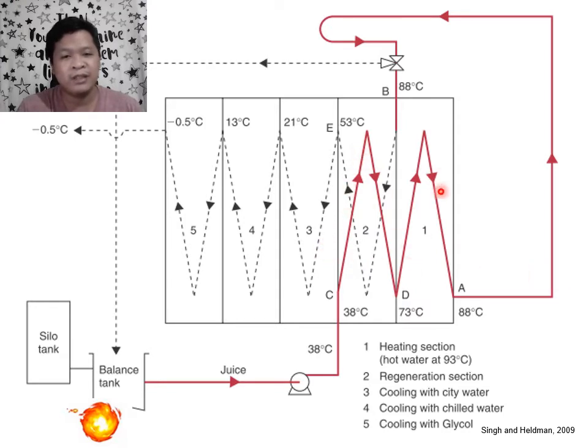The temperature increases. Okay, and then at the same time, dun sa cooling process niya, makikita mo, kasi kailangan pag na-pasteurize, rapidly din siyang i-cool to around refrigeration temperatures or close to 0 degrees Celsius. No? So, there are certain heat exchanger designs wherein yung na-pasteurize nga na fluid is also being used to initially heat up the cold fluid. Of course, there may be cases wherein you would need to add another heating or cooling medium for the next phases of the heating or cooling process.